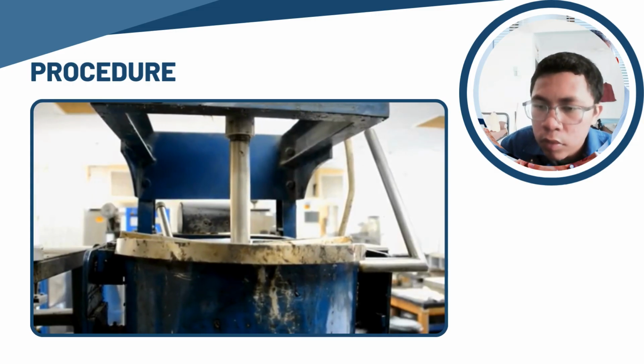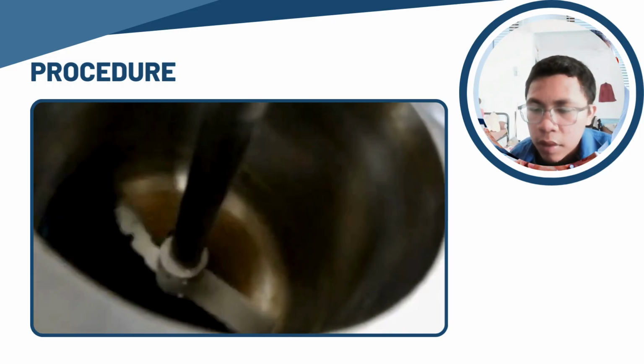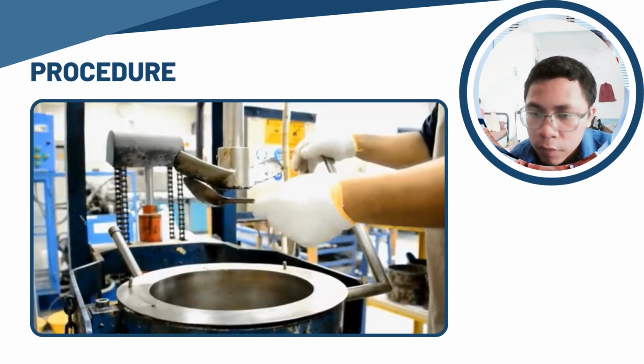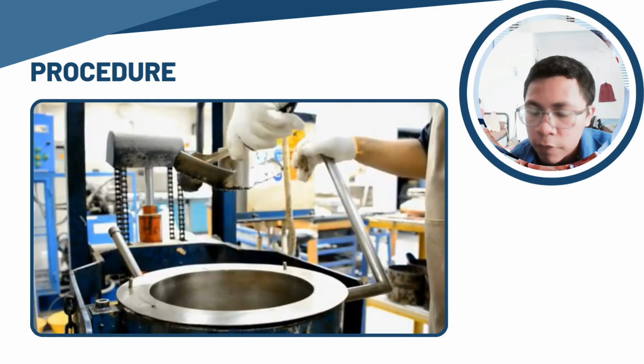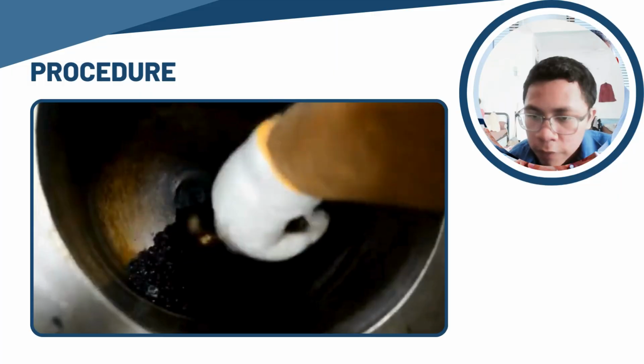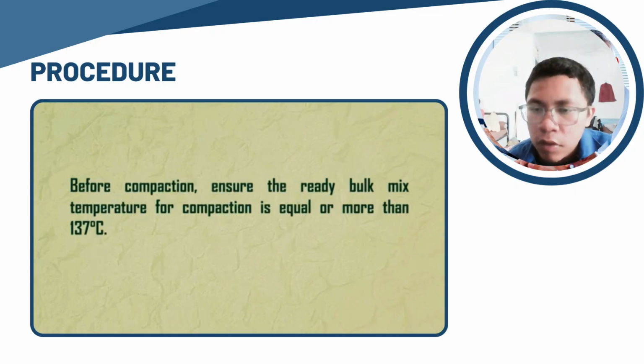Use the scoop to transfer the asphalt mix into the mold. Next, use the heated spatula to roll the mix vigorously 15 times around the perimeter of the mold and 5 times over the interior. This process ensures a smoother specimen and eliminates any bridging of the rock.